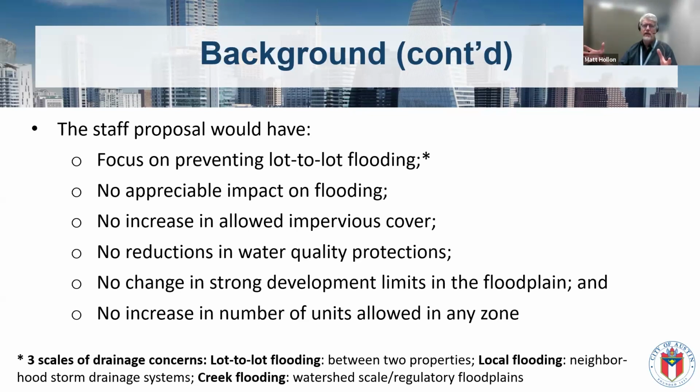Those are very big areas that drain to large creeks, and we have regulated floodplains in those areas, and we look at that scale. When you're talking about individual tiny subdivisions and site plan projects at this multifamily level of 5 to 16 units, you basically cannot tell what's going on when you do the modeling or see that in reality. That's not the level of impact we're going to see.